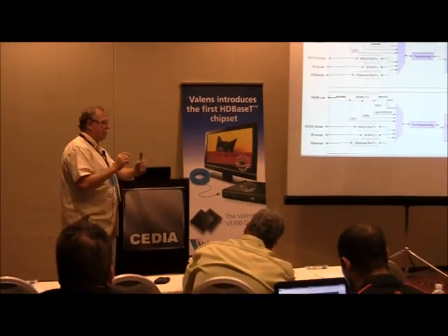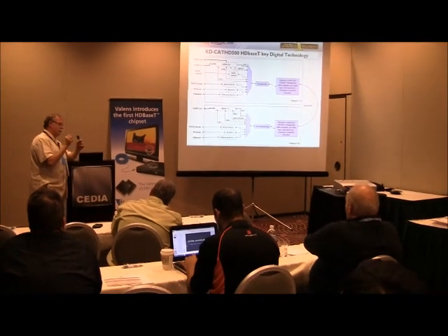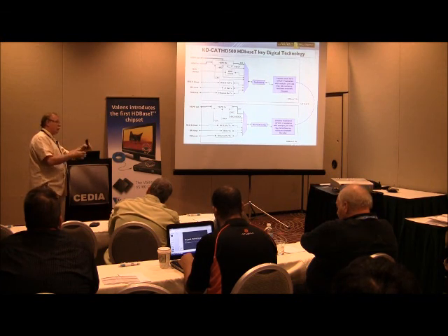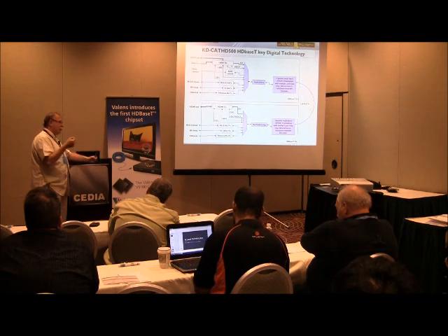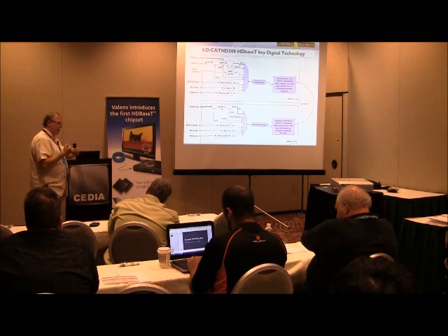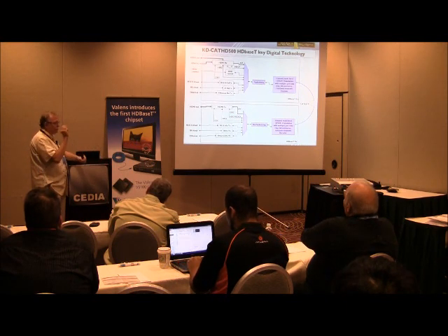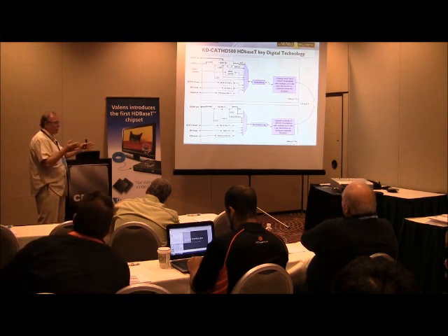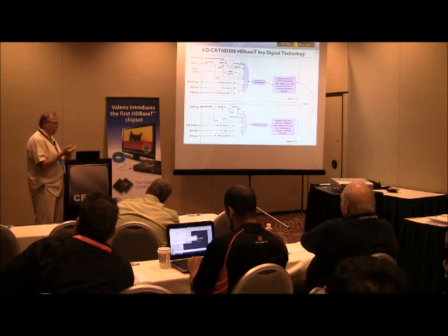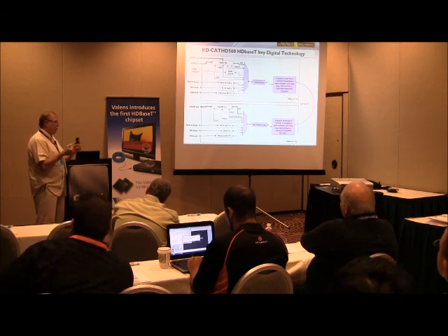Well, the way it looks is, EDID is a file. It's a file that is recorded in a small chip that is mounted next to the HDMI connector in any TV set. The EDID, by definition, is powered by the HDMI connector power. So even if the TV set is not plugged into the wall and you connect your cable TV box to it, the cable box will already read that EDID information using that power. It's a very tiny file, 64 bits or 128 bits, that has information about the TV set's resolution, audio formats, aspect ratio, maker, and many other components.